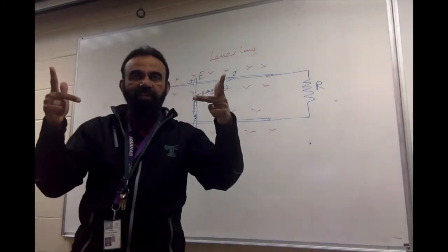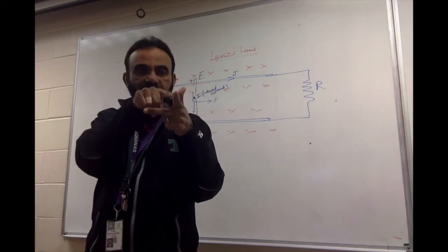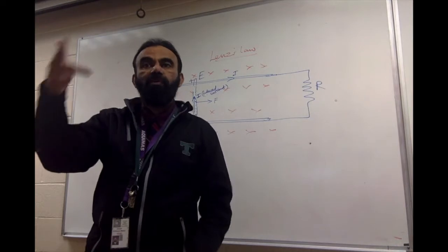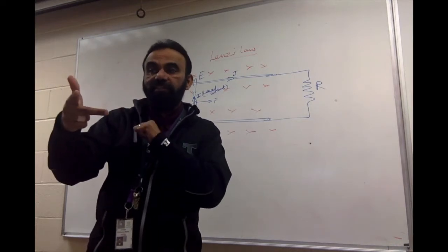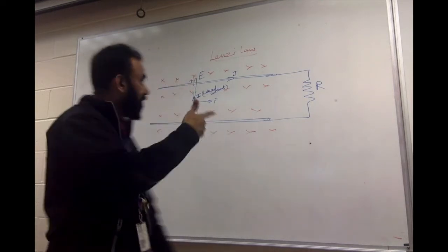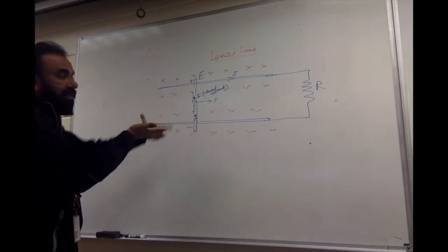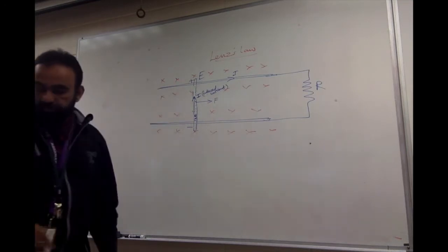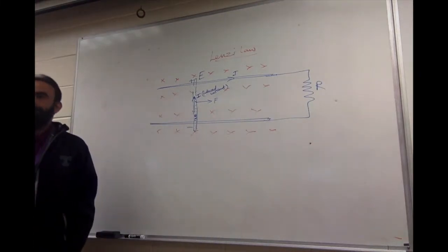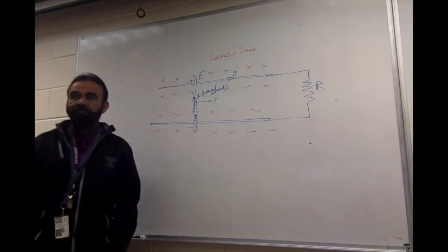The difference between left hand and right hand is this. On the left hand, you are sending a current in a conductor placed in a magnetic field, and the conductor experiences a force. What is happening here? You are not sending the current. You are moving the conductor that way, and induced current flows in this direction. Force is, you're forcing it to go this way, and the field is inward, so the induced current is upward. So this will help you to find that. Is that clear?